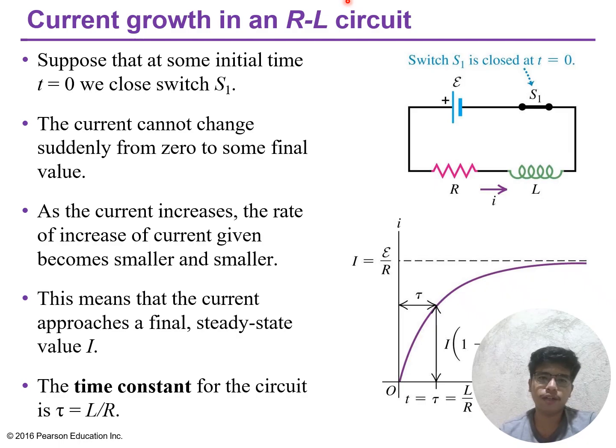The time constant tau equals L over R. After 1 tau the current reaches 63%, I mean about 60% of I sub F, and after 5 tau about 99%. The graph shows I starts at 0 and curves upward, approaching the I sub F horizontal line. In steady state, the inductor acts like a short wire, and X sub L is irrelevant for DC. So current flows steadily through the R.